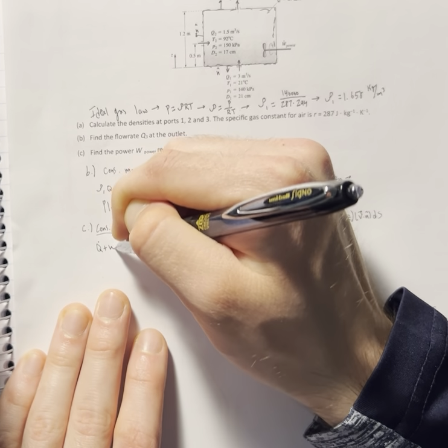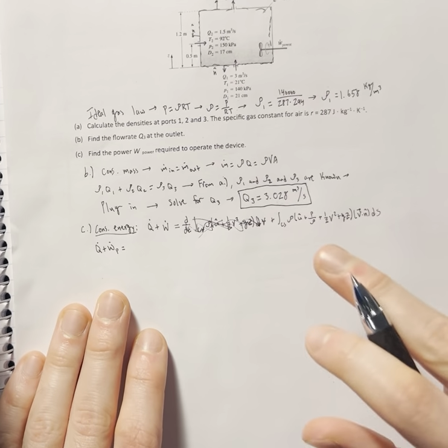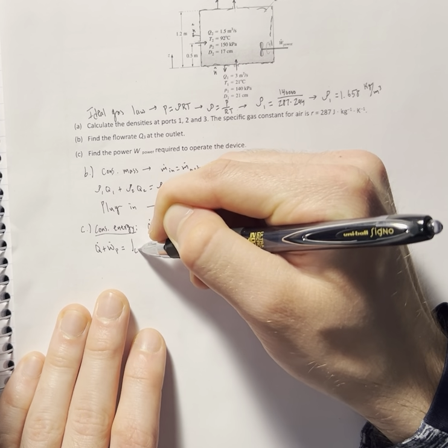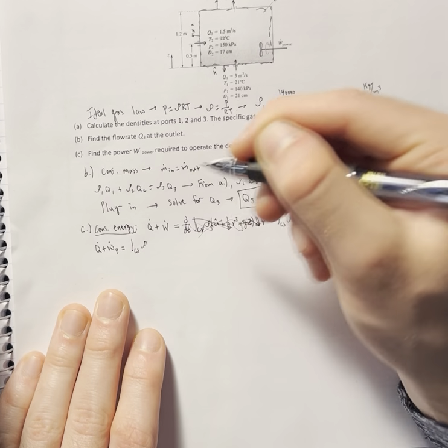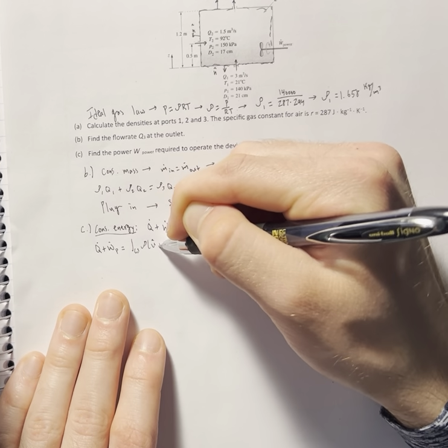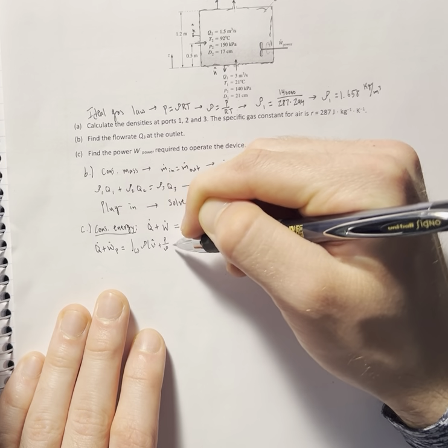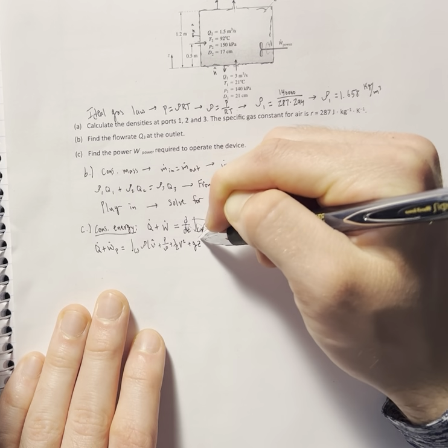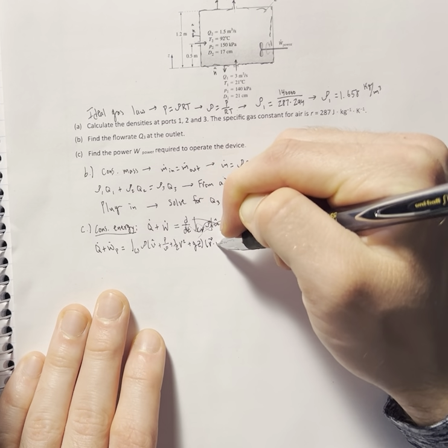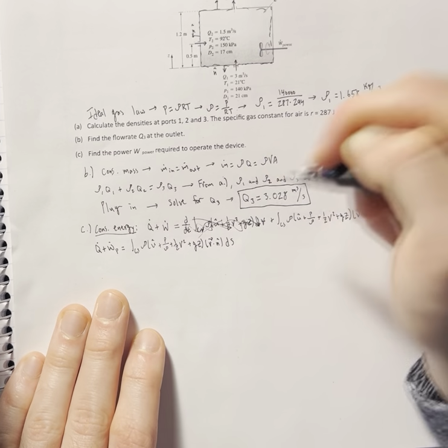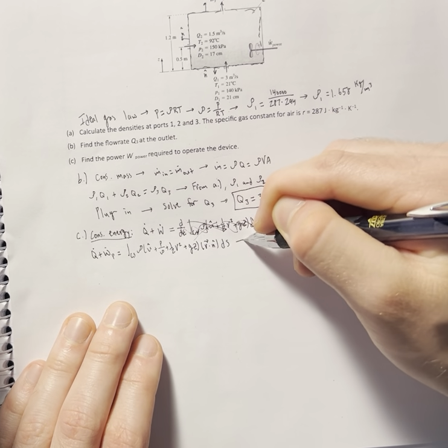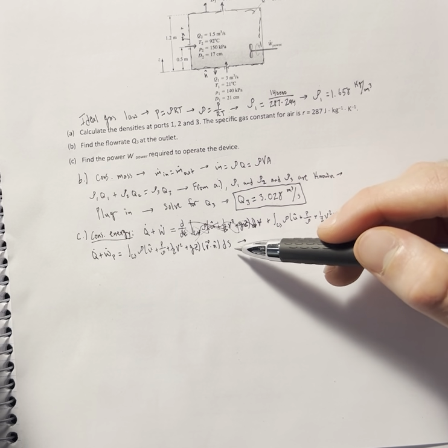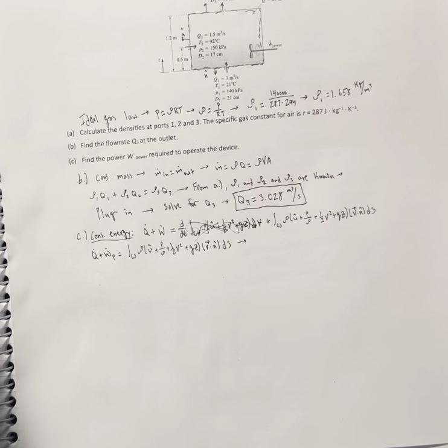So Q dot plus W dot P is equal to all this stuff over here, okay? So I'm just going to rewrite this. And I'm even going to rewrite this further and say, since everything is 1D inlets, this V dot N and this dS just simplifies to the velocity and the area.